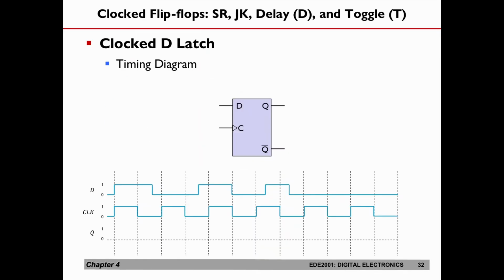So this is the first flip-flop circuit that we are looking at. This is what we call the D flip-flop. Now, the name clocked D latch is a very loose name for the D flip-flop. The proper name for this is a D flip-flop because this is clock edge triggered. This is no longer level triggered. So rightfully, this is a very loose name for the D flip-flop. Now, let's take a look at how we can analyze how this D flip-flop works.